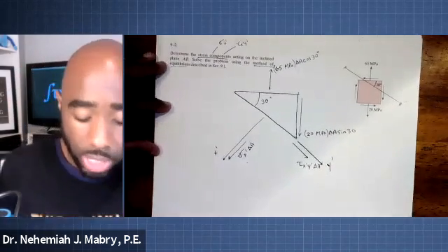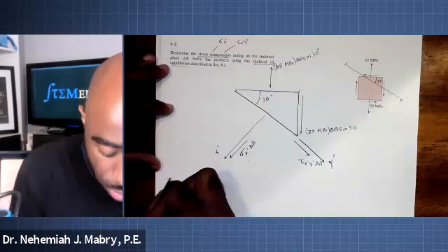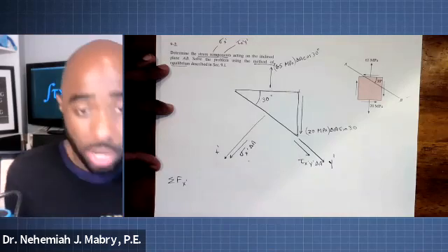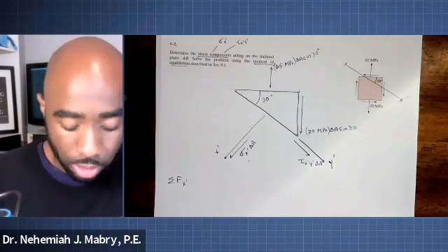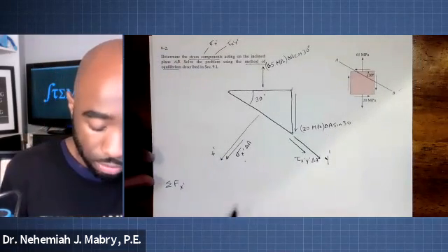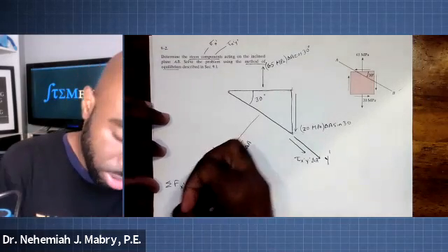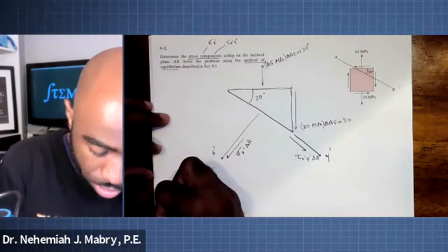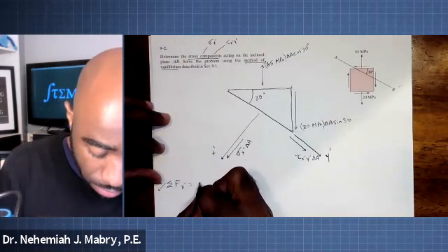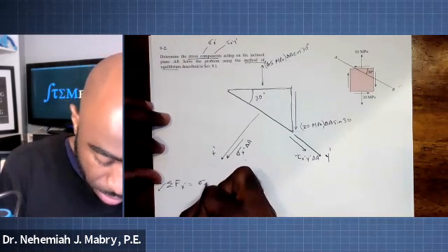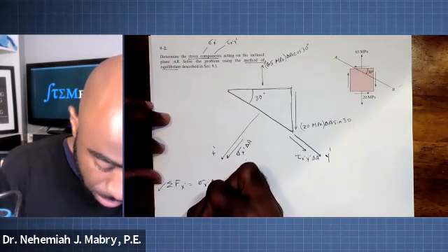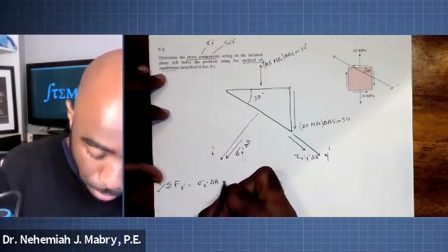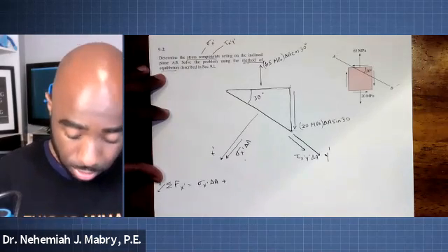All right, so let's do the equilibrium method. We're going to sum the forces in the x prime direction. That's all we're going to do right now. We're considering this the positive direction here. We're going to keep it in line with how we drew it. So we have sigma sub x prime times delta A plus.